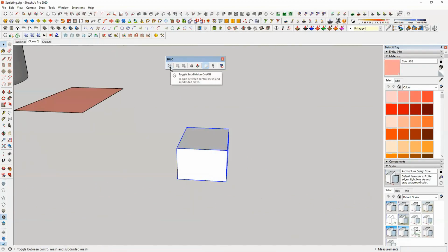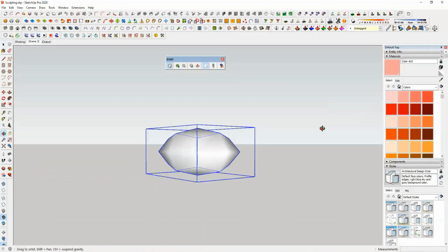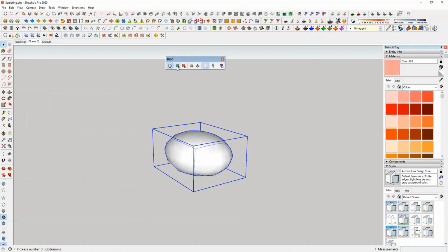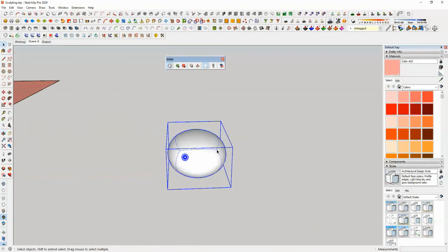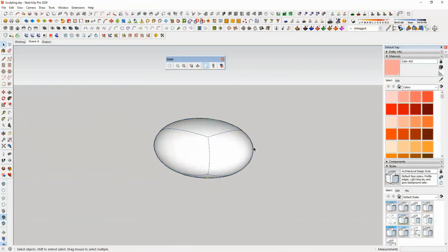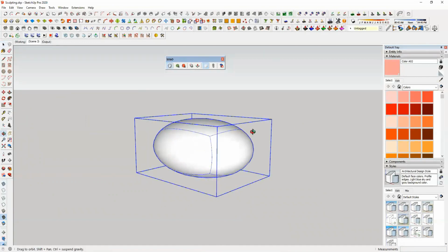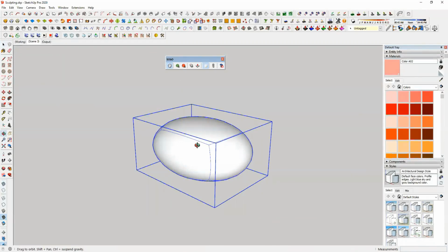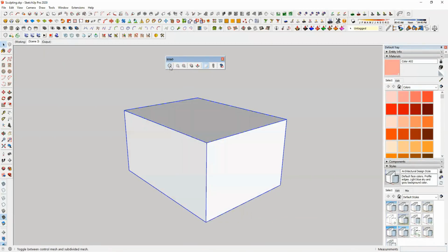And if I click on subdivision on and off, we had turned the subdivision on, and I can increase the number of subdivisions, similar to the number of iterations in that case. By clicking this icon several times, I had clicked 2 times, and we have this shape. So the benefit of using subd is that you can turn it on and off.